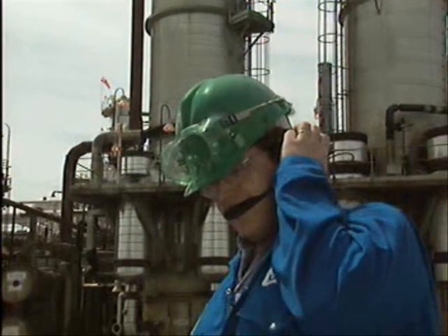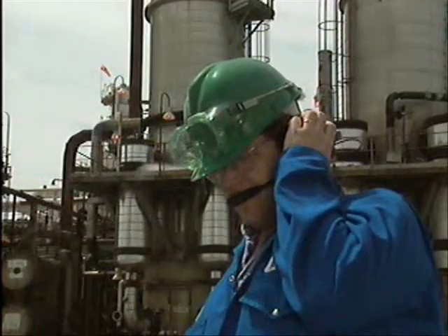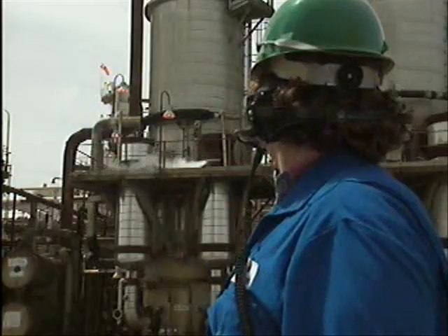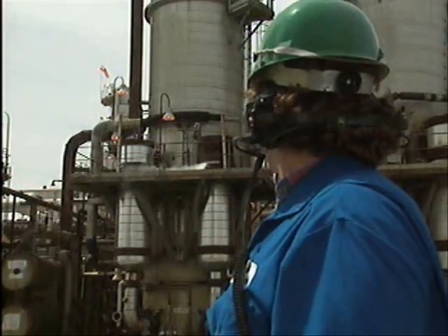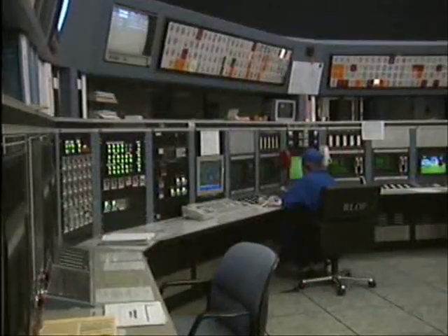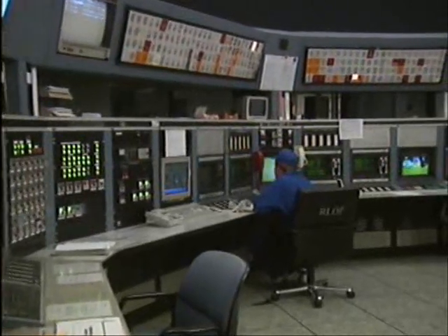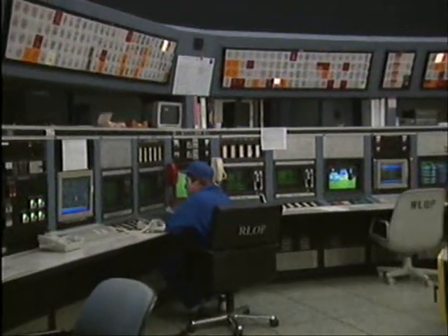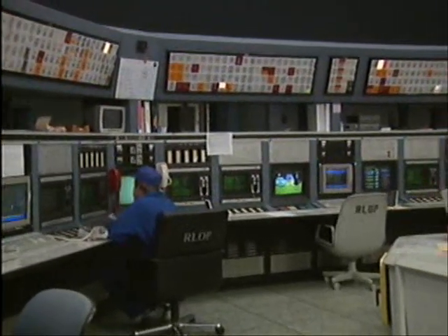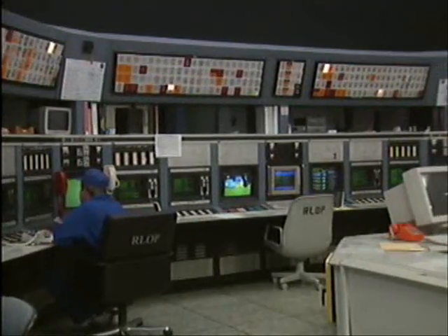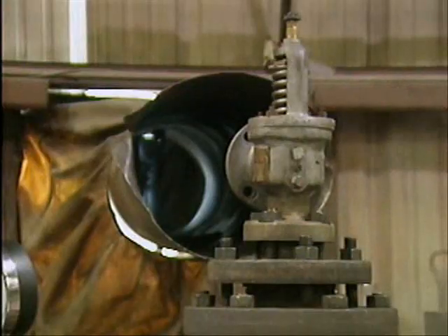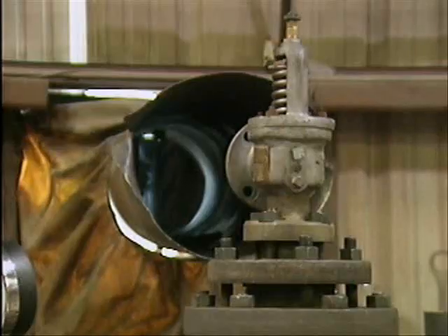So before you hand lift a valve, notify the appropriate operating personnel so that they can compensate for the drop in system pressure and keep it from interfering with normal operations. If operating personnel aren't forewarned, when pressure drops as you hand lift the valve, they might take emergency measures to raise pressure or to shut down the system. Such actions could be costly and perhaps dangerous. Likewise, before hand lifting a valve, you must take appropriate personal safety precautions.